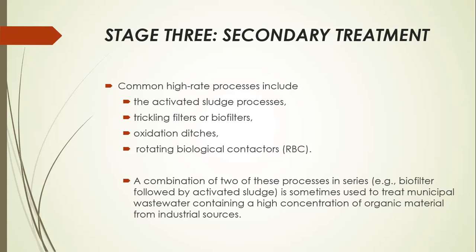Again, as I indicated earlier, unlike the activated sludge process, this is the opposite of it. In the activated sludge, both microorganisms and the wastewater are kept in suspension. But here, the wastewater is not moving, whereas the medium is moving, the biological contactors.